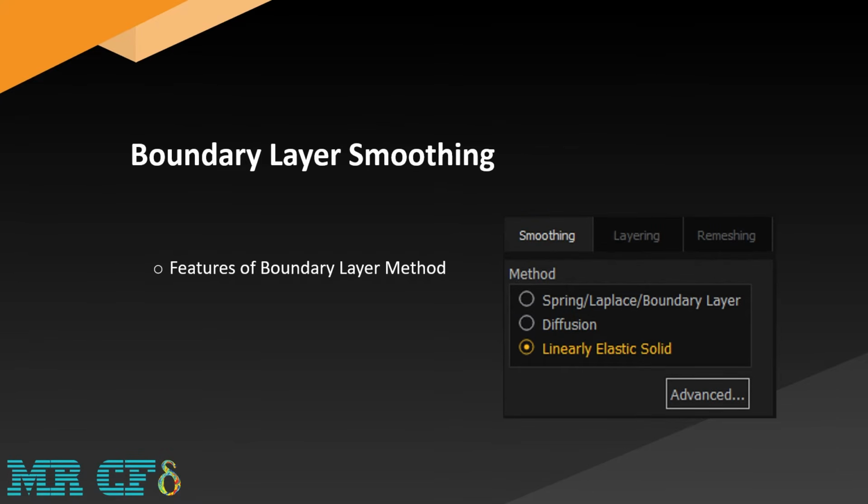Now, when the boundary layer smoothing method is activated, the nodal coordinates of each cell in the boundary layer area are updated due to displacement with the same displacement vector. As a result of the boundary layer smoothing method, the cells adjacent to the deformable wall are deformed to maintain the quality of the boundary layer region. Typically, this method preserves the height of boundary layer cells adjacent to the deformed plane region. This is primarily considered for translational movement because if the plates undergo significant rotation, the cells of the boundary layer may become skewed.